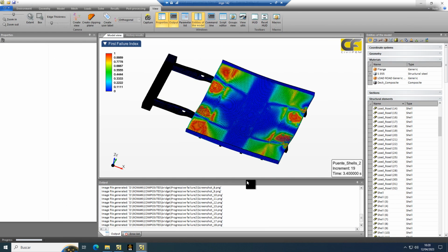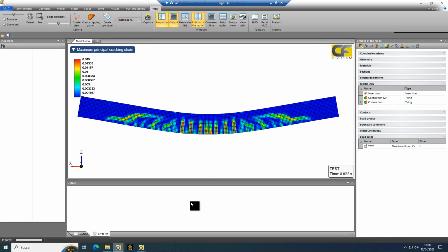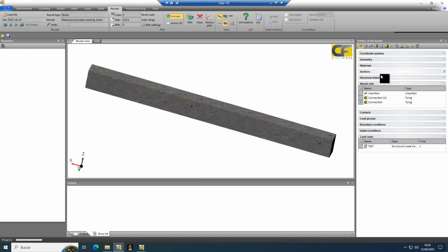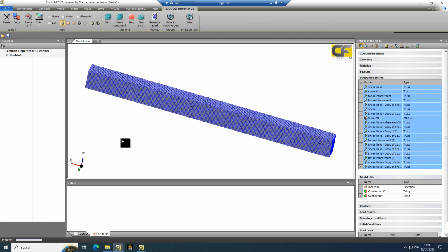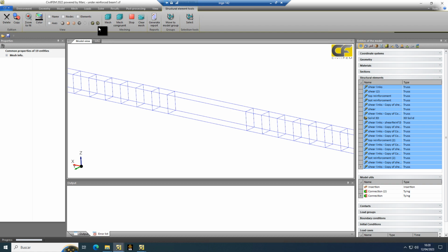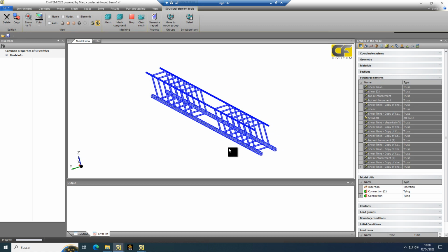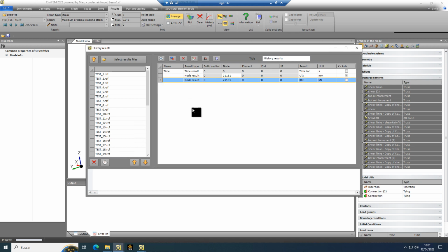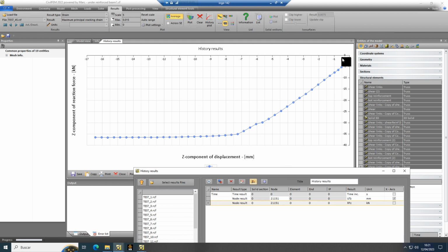So if we go to those models, we can see that the original situation is this with the concrete beam. In this concrete beam, we have solid elements for the concrete, and inside it we have rebars, given here with the thickness, that are modeled with truss elements. In this model, we analyzed the force versus displacement, and we obtained this curve: vertical displacement versus force. We have here the first crack, and there's a different slope in this part, and then here we start having yielding on the steel until the collapse.